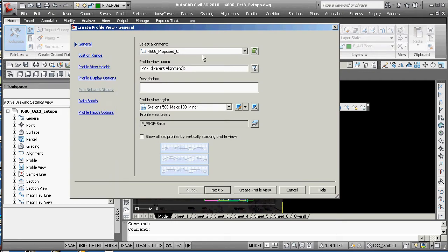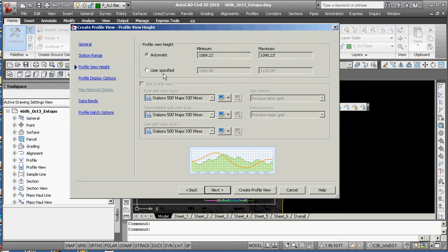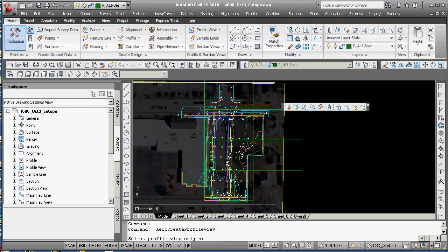You're going to be proactive about grabbing the right alignment, looking at the range, 1100, at the height, and not grabbing what it gives you, but going to something like 1060 and multiplying. You'll see later on that multiplying by 10, you're going to create a profile view. Then you give it the origin. You type in 1100, comma 1060, and you know it's going to be off by basically this scale times, I think, 100, but it's not going to be perfect. You hit that there. It's now created.